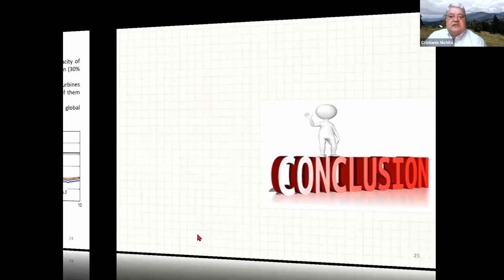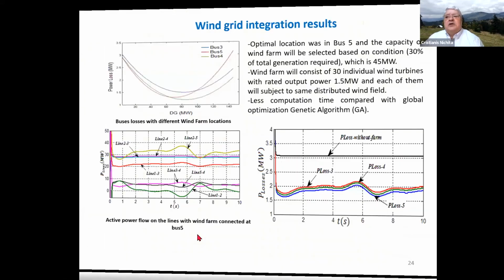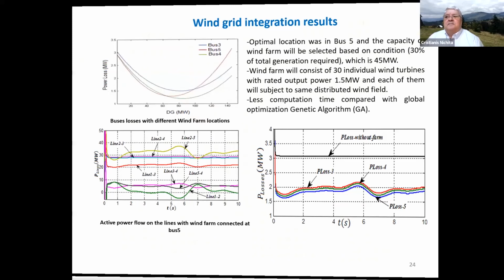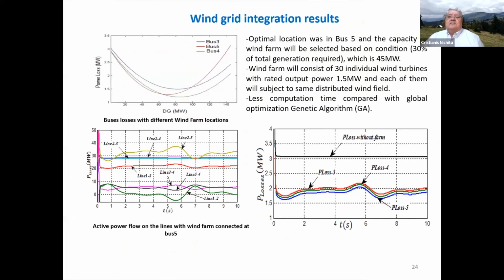The results are interesting because, for example, for the case of the 5-bus system, the fluctuation of the wind power output due to the wind speed variation could change the calculation of total real power losses within 30–40%.